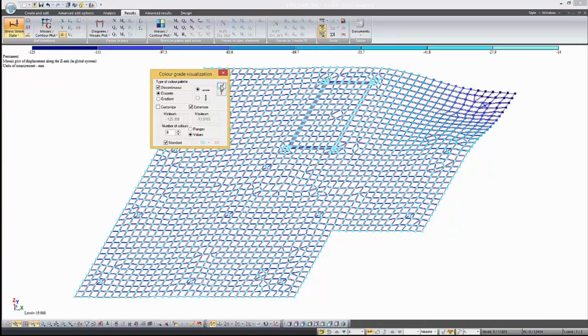Let's look at what the For extremum radio button is for. If you make the button inactive, the fields minimum and maximum will be available for editing. Suppose we are interested in the values of displacements only for -50 mm and above, while the remaining values do not interest us. In the maximum, set the value -50 and confirm changes. We see that the values less than -50 are painted pink. Thus, it is convenient to analyze the area of interest. Restore the view of the whole scheme.